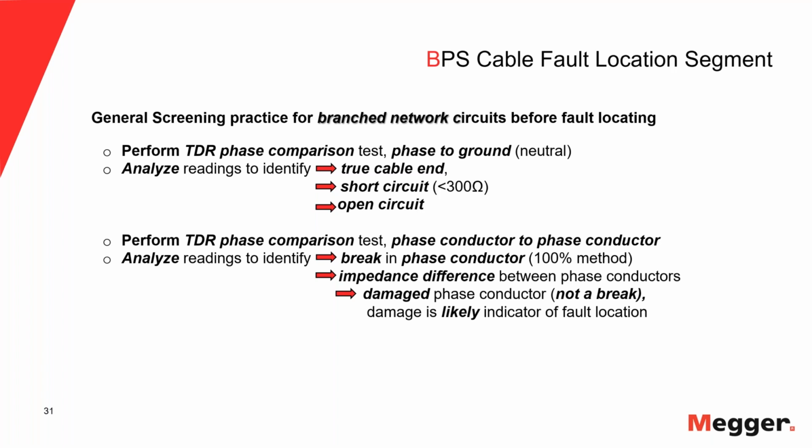So that's why I'm saying the insulation resistance reading gives you a good indication, and the fact that you can go from the substation can save you a lot of time.